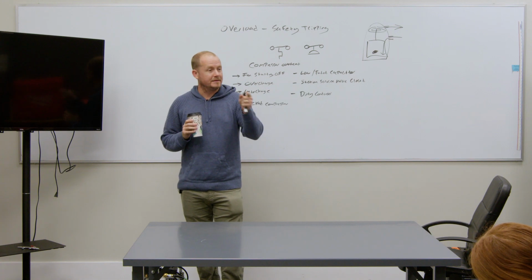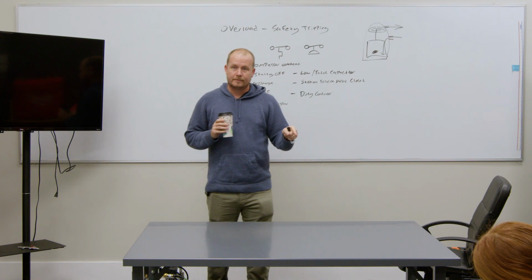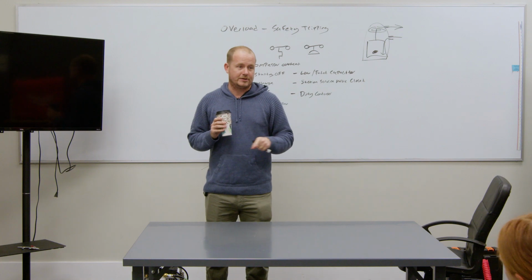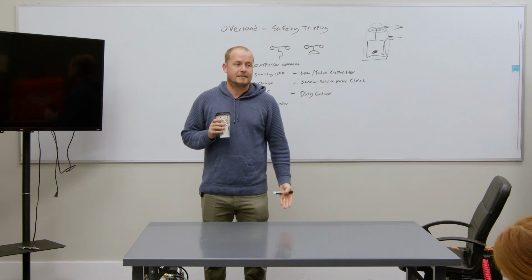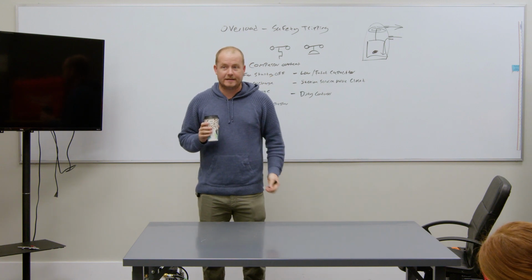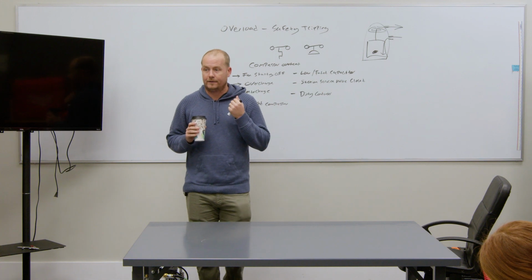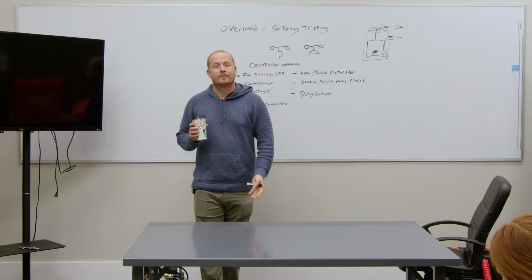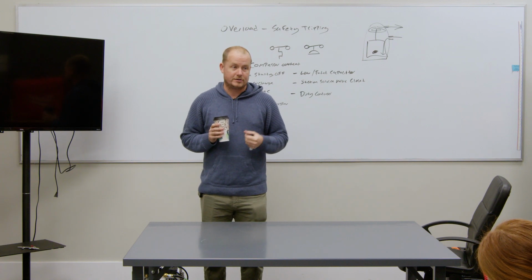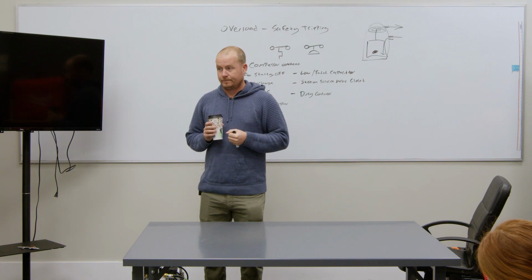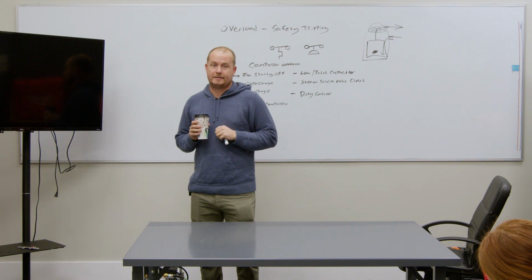If that heat stays in that refrigerant, this comes down to basic pressure and temperature relationships. Increases in temperature result in what? Increase in pressure, right? And so as that heat remains in there, that temperature just keeps going higher and higher. That heat can't be rejected out. That pressure also just keeps going higher and higher. And as it does that, the compressor is doing more and more work. It's pushing against more and more.